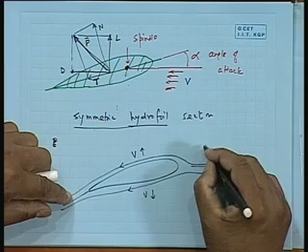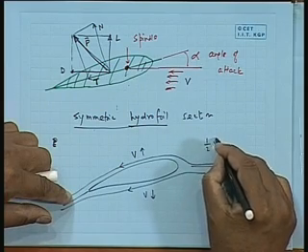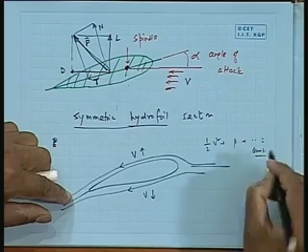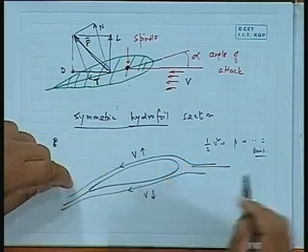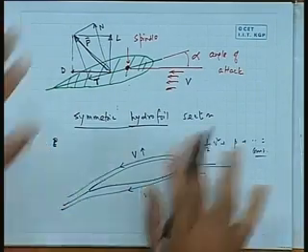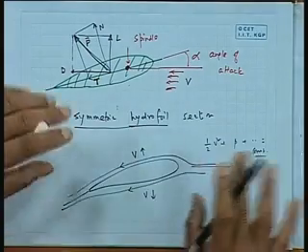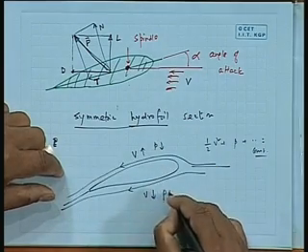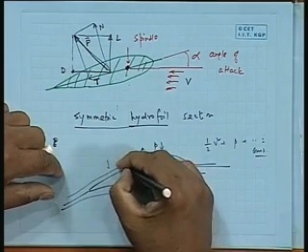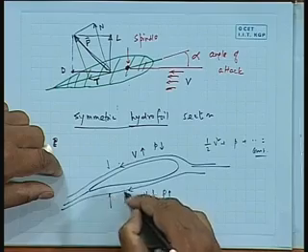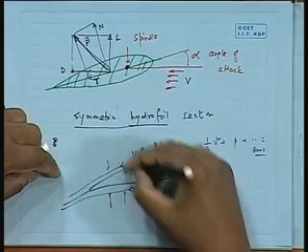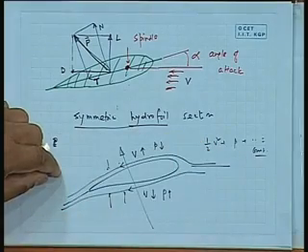As a result, Bernoulli's equation says that half rho v squared plus p plus rho g h equals constant. There is a famous theorem which says that velocity squared plus pressure plus some hydrostatic head is constant. Now, it has the same hydrostatic head, therefore, v going up means p coming down, and this means p going up. So, there is a larger fluid pressure here, more pressure than on this side. So, the net thing will give me a pressure on this side. That is why there is a force that ultimately comes out this way.